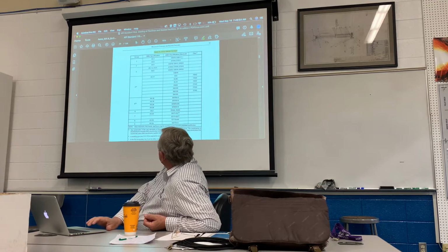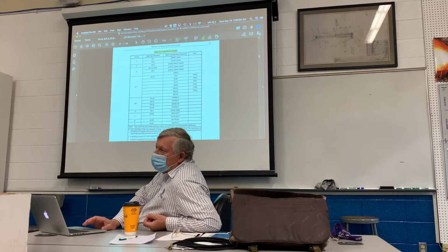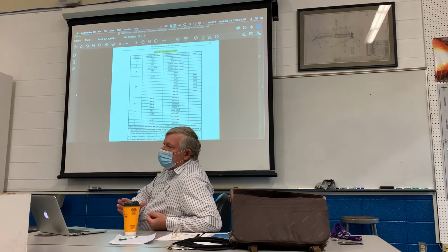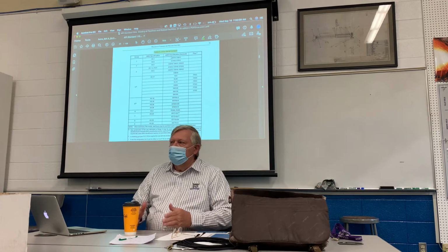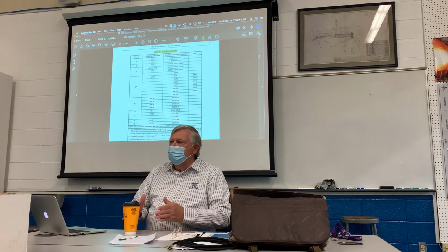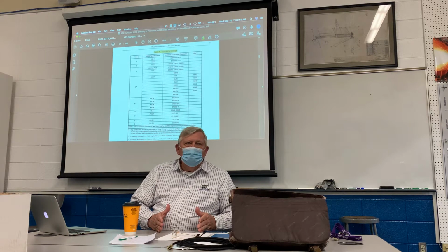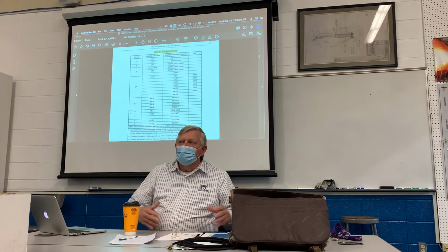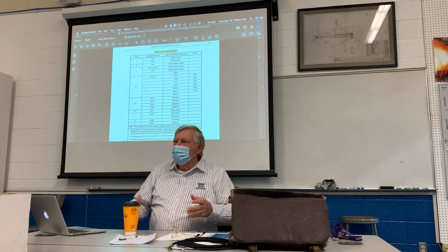AC machines, and they were using 6010 to do the welding, and the ships were breaking in half and sinking to the bottom of the Panama Canal and things like that. And they realized that they were using an electrode. Anything that ends in a 0 has to be done on DC. So they were using an electrode that should have been used on DC, and it was sort of an oh my gosh moment, because now they have all of these welders all across America, and everybody's using 6010, and the machine's an AC machine.